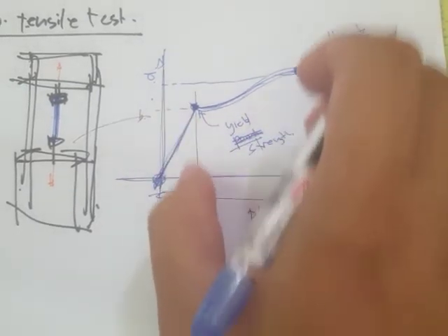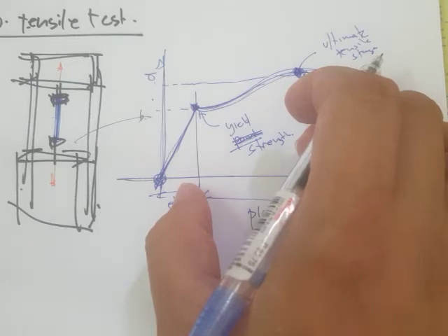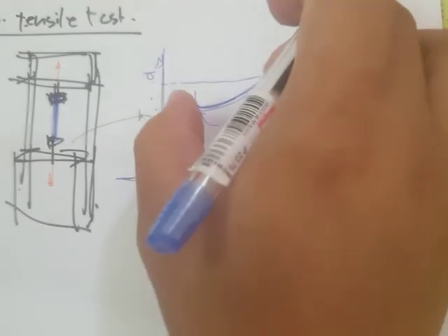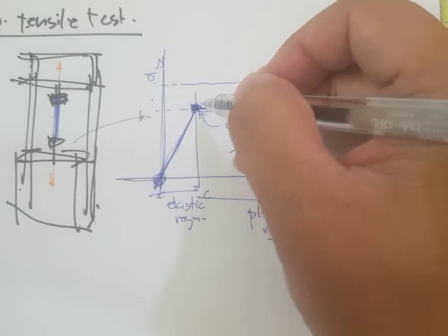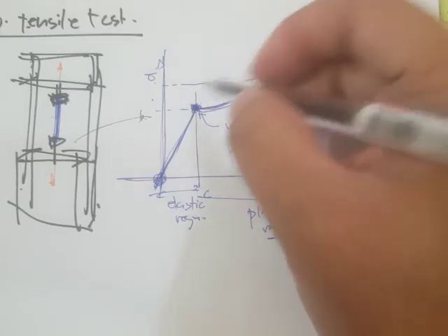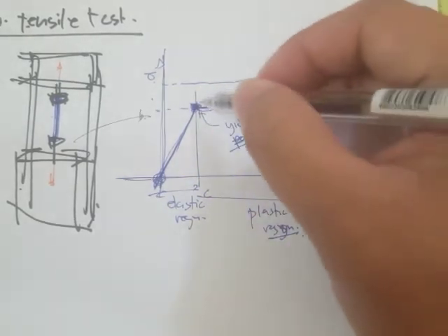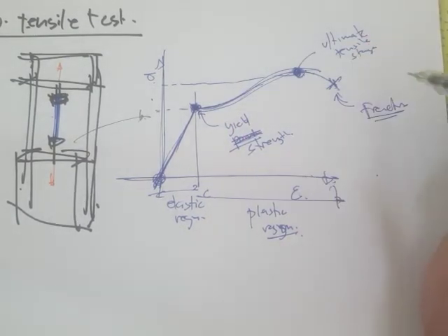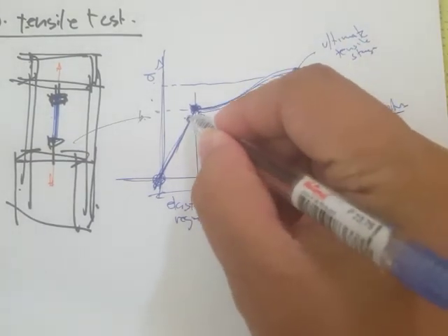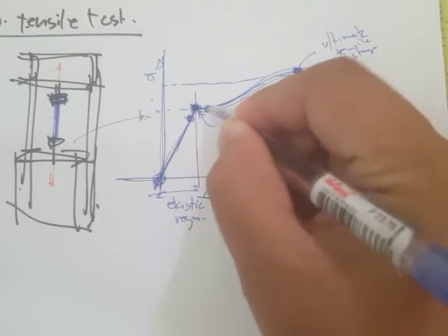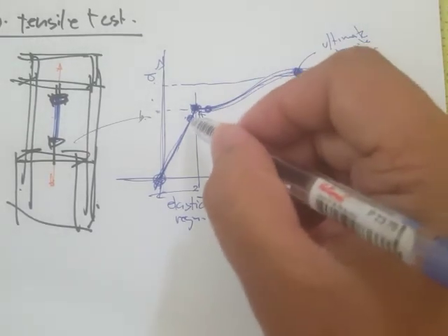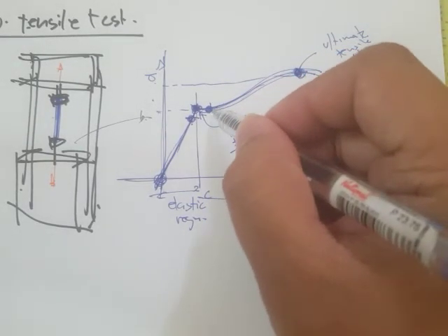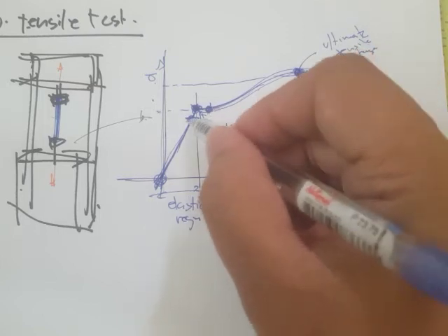And there's actually a lot of things going on, like if you read the strength of materials text, there are also necking and other things like that. But I don't want to focus on those things for now, because the ones most commonly encountered in computations are this yield strength and this ultimate tensile strength. And for some materials, there are still other points right here, like the upper limit, the lower limit, the elastic limit, or the proportional limit. A lot of terms, and these are not present in all materials.